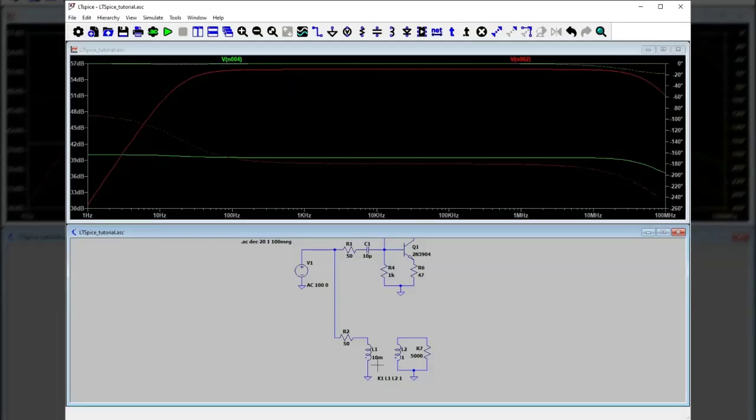That's a 100 times inductance ratio. And absent this command right here, if I delete that, I have a circuit that does absolutely nothing. I have a 50 ohm resistor driving an inductor and another inductor connected to a resistor. That's going to do absolutely nothing. All right. So I have to tell Spice that I want these two inductors to be coupled. How do I do that?